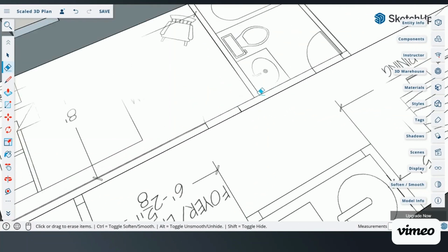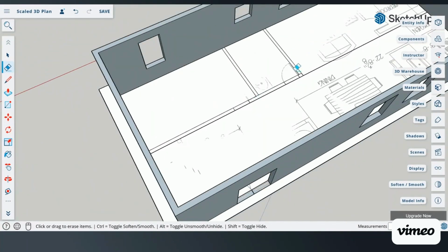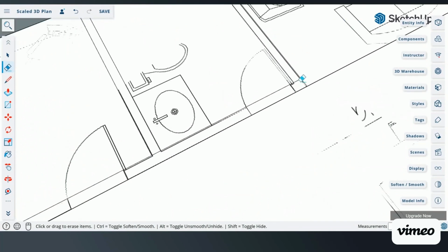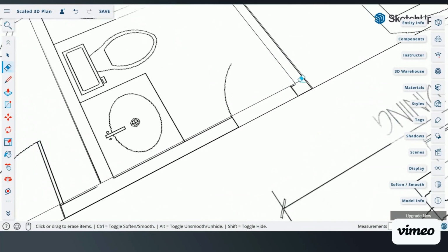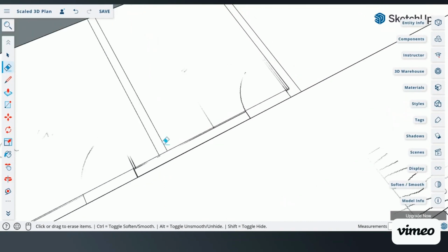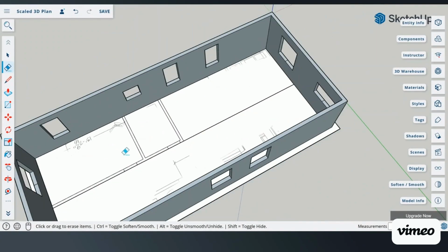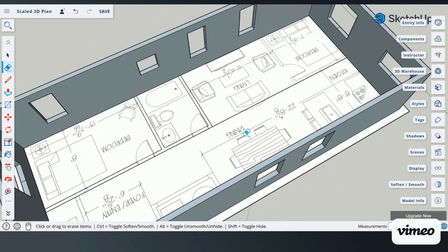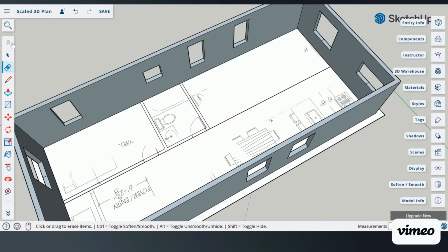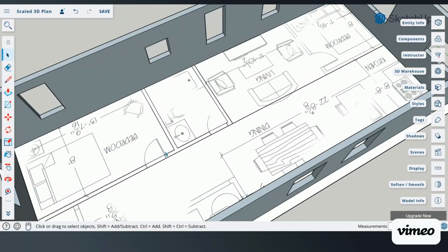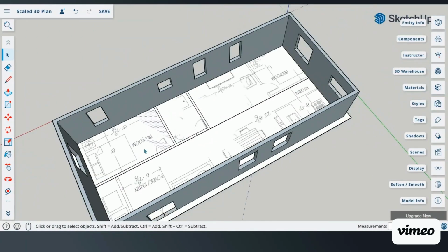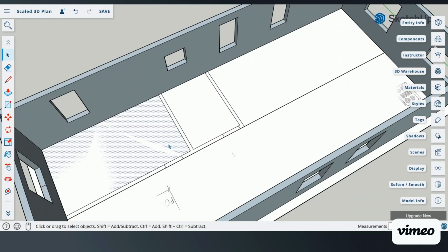There. And when you have things created, because I want to push pull things, I'm going to want these lines to move as one. So I'm going to delete some of those edge lines there so my walls can look continuous. Using that select tool, I want to get back inside of this group by selecting the group. And I have faces created.